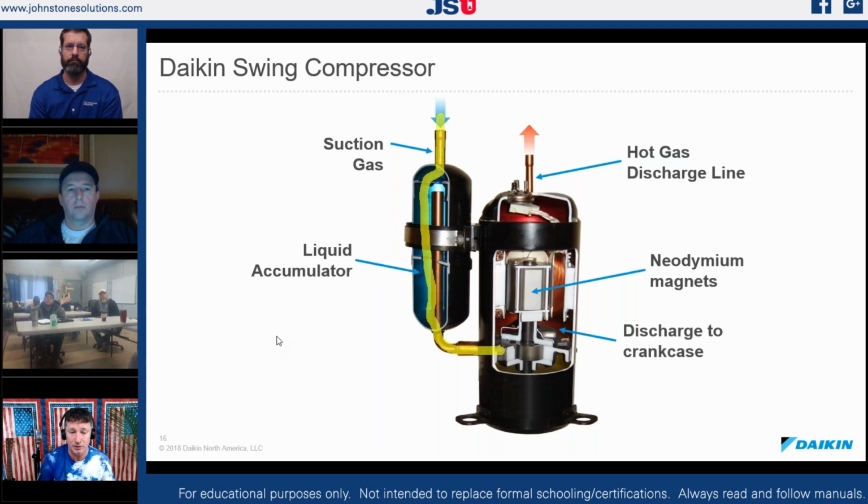That motor is designed to turn that crankshaft freely. It's not a high torque motor. It's a permanent split capacitor motor. Go put a hard start on the thing, let it sit there for a while. He said, okay, I'll run to my local Johnstone and get a hard start kit and I'll come back and see if I get this thing moving. I said, if it doesn't fire up, we're going to replace it no matter what. But just out of curiosity, I want to see if this is exactly what we are finding in the field.